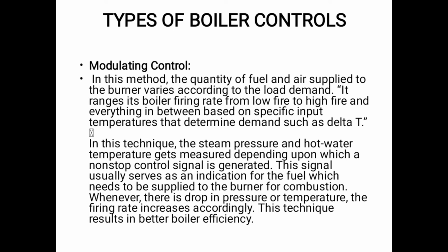In this control system, there may be a cascade control loop, and cascade control loops are used where we want a slow and precise response. So this was our modulating control system. The difference between the positioning system and the modulating control system is that in the modulating control system we consider the flow of fuel, the flow of air, and also the ambient temperature compensation.